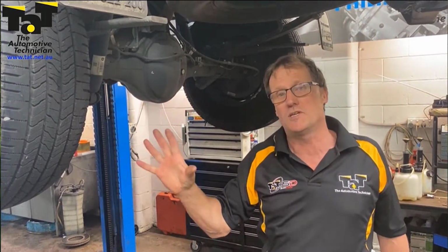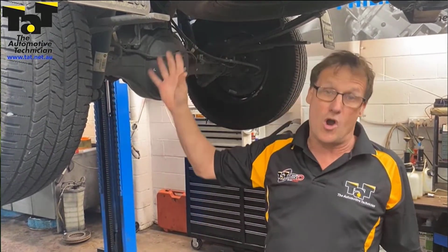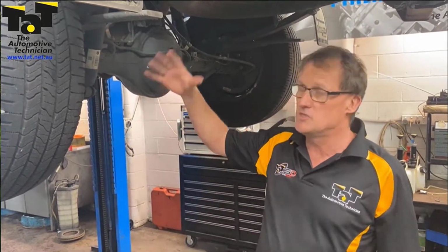I suppose with any car on a hoist nowadays with ABS and traction control and things like that, having a good look at wiring harnesses when you're having an inspection at a service is a great idea, especially looking at those pivot points where wiring has to pivot because it's on an axle or whatever, and so you're getting that wiring movement all the time.